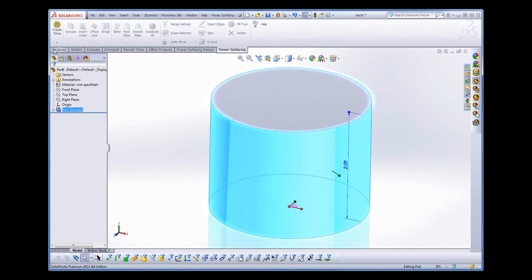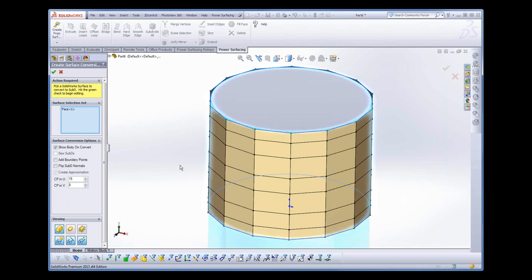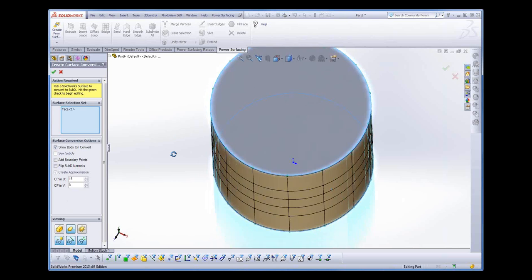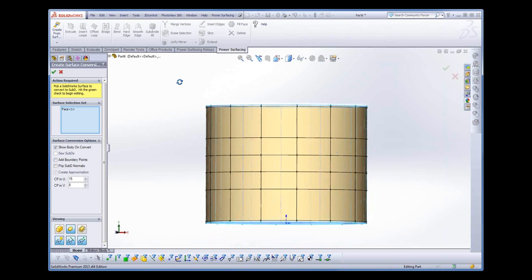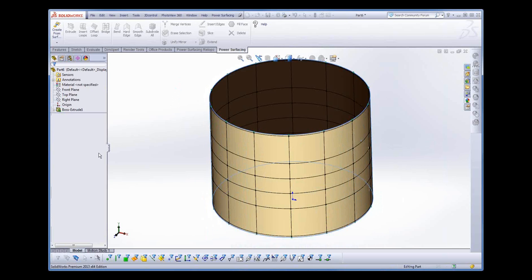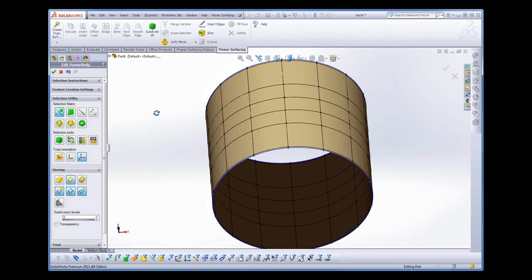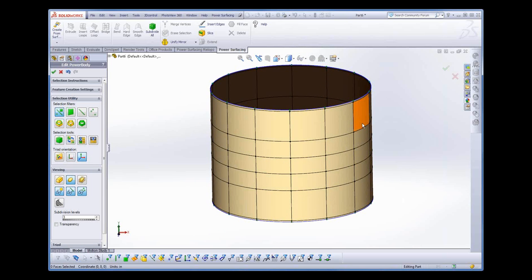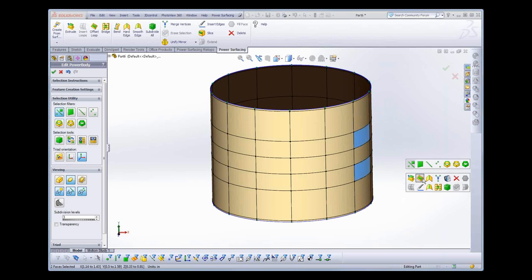Under our create options, we can do a create from surface. And remember, right now we're looking at the control mesh. If I switch it over to subD, you can see that it is the size of the surface there. It's an exact replica of the surface. And as long as you stay far enough away from the edges, the boundaries, you could go ahead and do more modeling on this if you needed to.